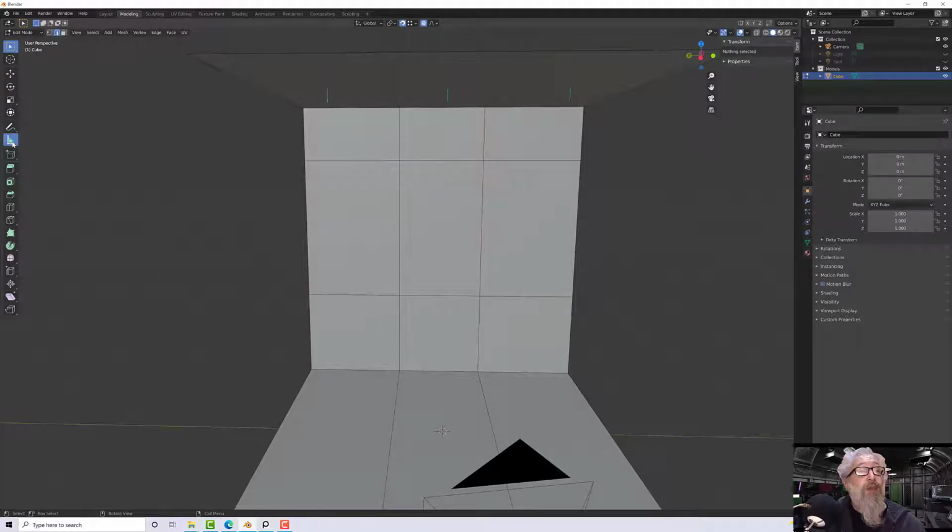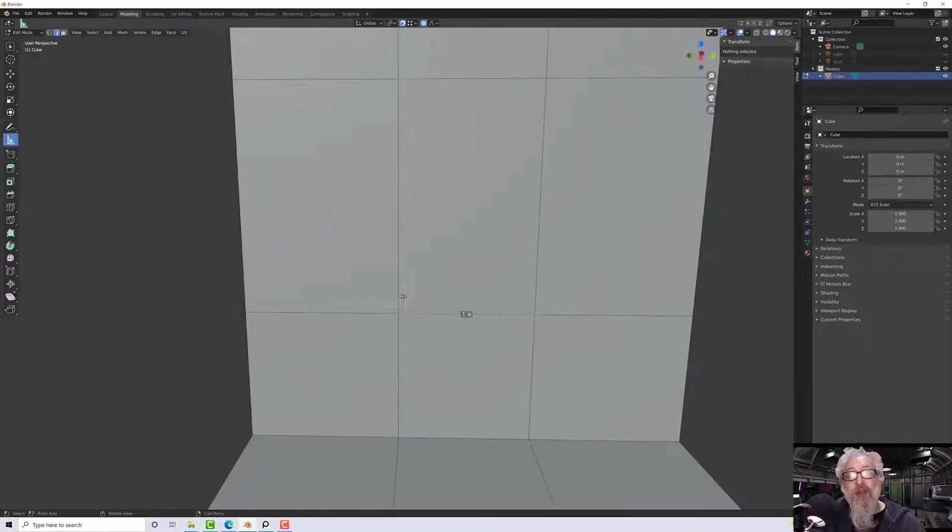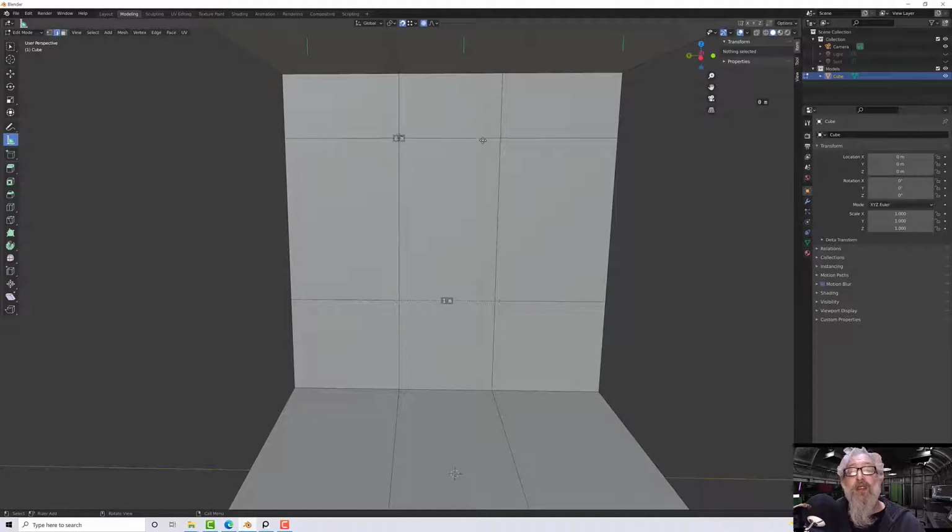And we can confirm that by going back to our measurement tool. You'll see we've got our measure there already, but it's measuring beyond that dimension. Whoops, I didn't hold down shift. If you want to delete a dimension, by the way, if you click on it and just hit delete, it will. It's pretty easy to do. There we go. So right click, left click and hold, and then drag that over. It's 91.44 centimeters, which happens to be 3 feet.